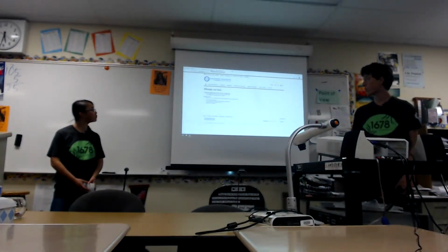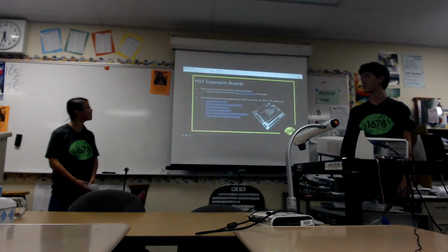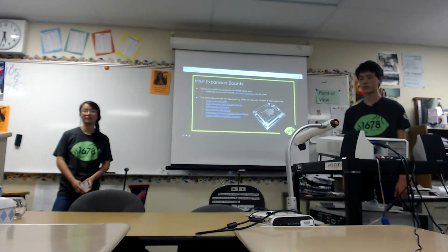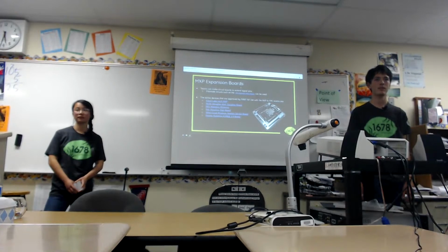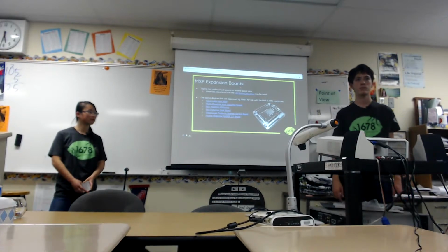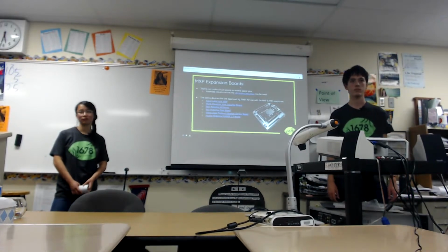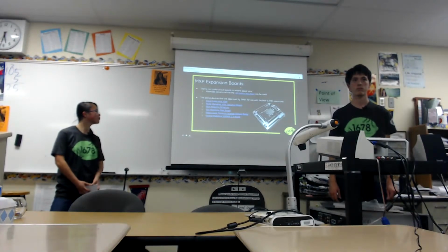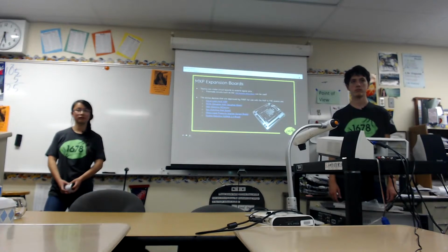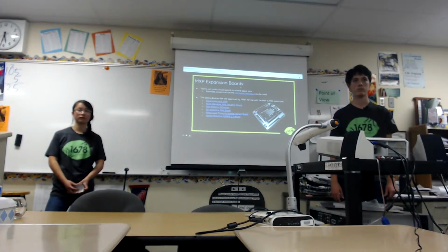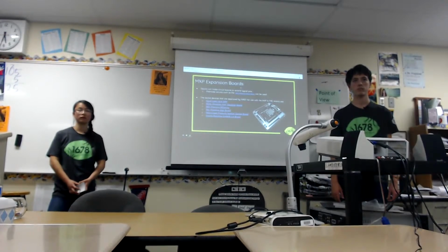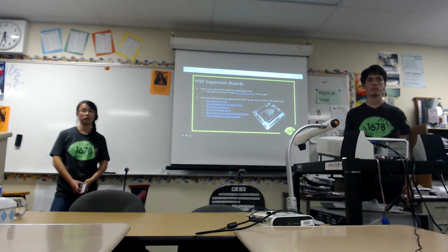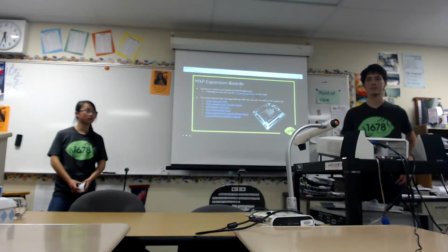No, it was designed by Team 971, the Spartans from Mountain View. Some of their current mentors and former team members, Austin and Travis Schuh, designed the board and had it built. To share it with the community, they worked with West Coast Products to make it generally available. It was a great way to deal with problems of getting PWM connected. Now that most of the motor controllers are CAN-based, it's less essential. It also helps protect your RoboRIO from bits of aluminum falling in it, which I think is very handy.